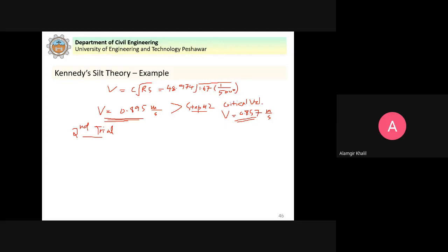You can see here that V is inversely proportional to the area. Q divided by area A, that you get the velocity. Now this is the actual mean velocity. I want to decrease it, so it means that I have to increase the area A. So it means that we should increase the depth. Clear?